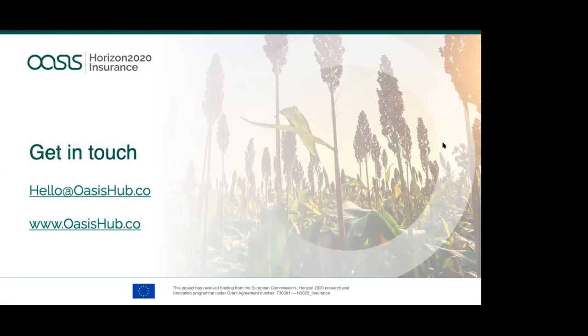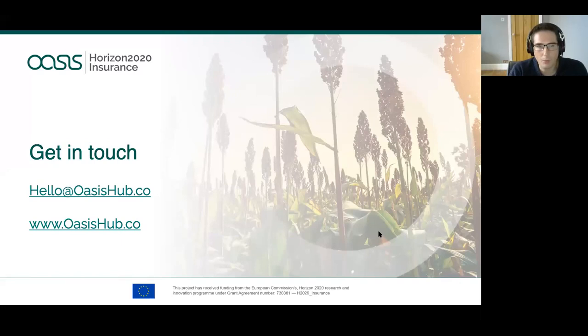The last question: for the Australia CAT model, are the 50,000 synthetic events validated against historical flood outlines? Yes, a few of the synthetic events have been validated against past events. I mean, that's the way to go forward. We have just about all the major flood events in the model as well, which is one way to make sure that your calibration is accurate, because that will test the vulnerability components as well as the hazard components.